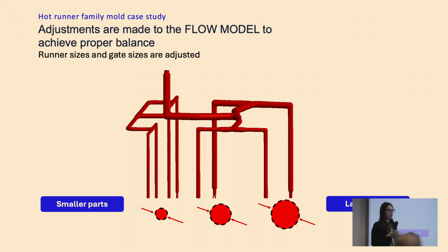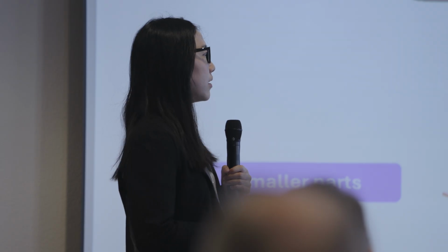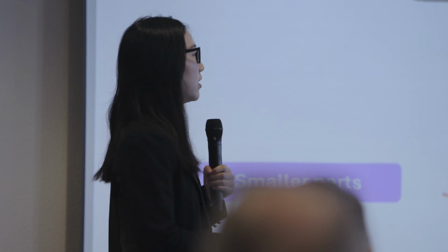As Ray just mentioned, in traditional trial and error, you may have to create a new mold and then do a mold tryout again, and then shoot a part and check the dimensions to see if they are okay. But every time you do a mold tryout, a new mold has to be created, more material has to be injected, and that's more waste, that's more cost, and that's less efficient.